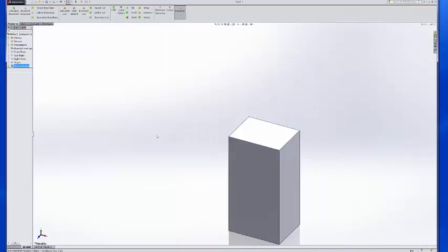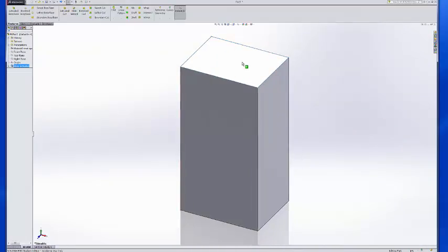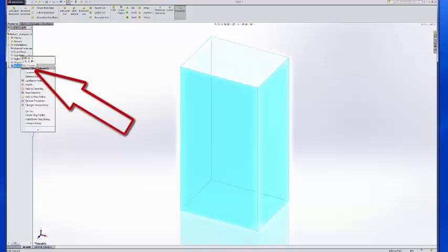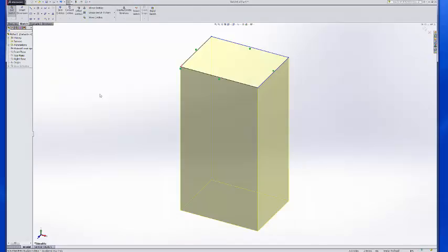Now the only problem is now I do need to control the size of that box, but I wanted to show you you can do that without inserting the dimensions on there. But again, it just is not the preferred, at least in my opinion, preferred procedure. So right now I'm going to right click on that boss, and I'll go up here and edit the sketch. Now you've got edit feature and edit sketch. Edit feature will allow you to change the thickness of that feature. I'm going to go back to edit sketch, and it's not moving to that plane for view,